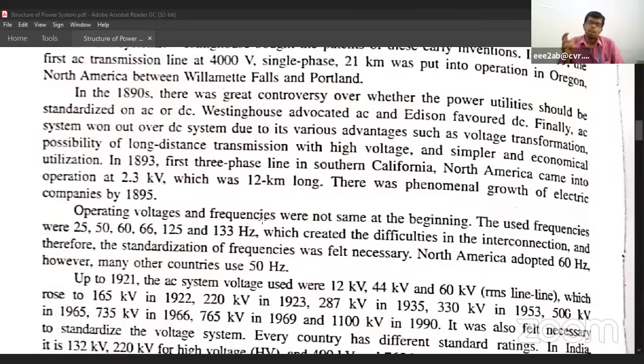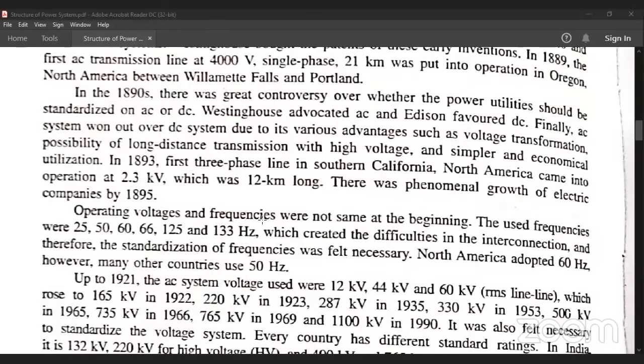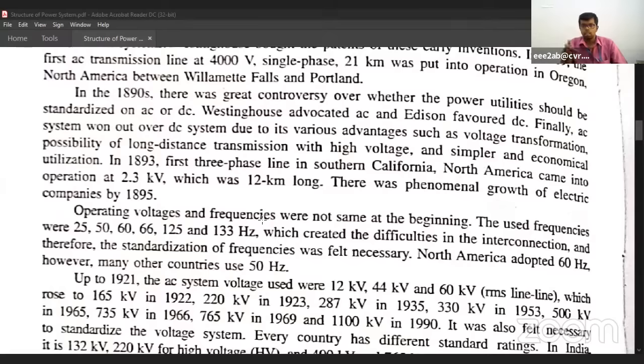That's why you find it on your iPhone adapter. That adapter can work on 110 volt, 60 hertz also, as there are two modes, and it automatically turns to the right mode. So even if you take your iPhone charger to the US, you can use the same charger in India also. It works on 230 volts 50 hertz, and on 110 volts 60 hertz.